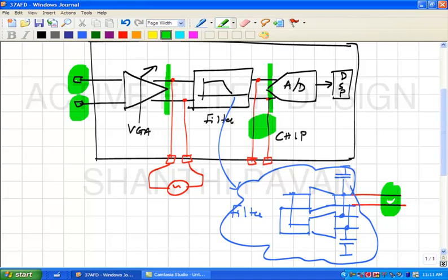That is exactly what we are doing now. We are tapping the output of the filter. You understand? Okay, so what do you think are the problems? We should put a voltage buffer. That is the solution. What is the problem you are trying to solve? Let's say integrating capacitance. So, to give you an idea of why this is a problem, this side of the crowd, do you think there is a problem or there is no problem? Measurement equipment can also. What about the measurement equipment? That you also have an impedance.